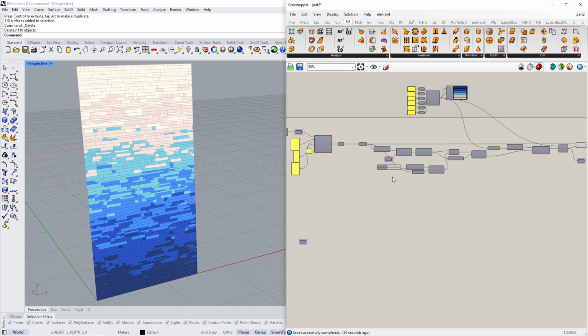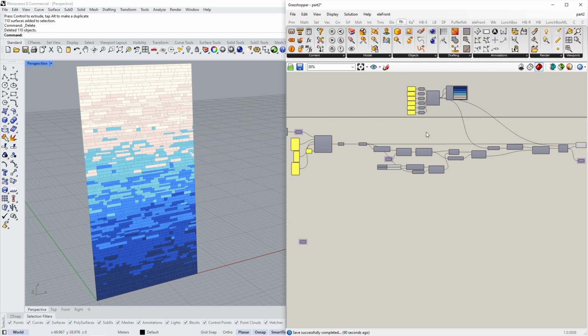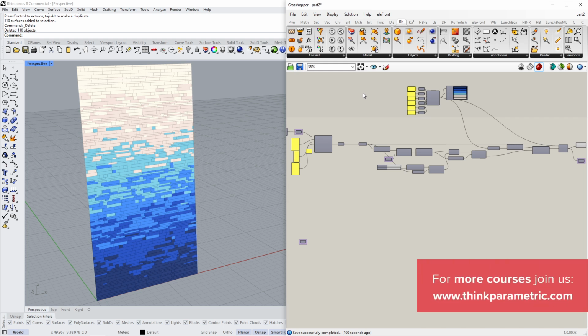And we're going to take a look finally into this new tab from Rhino, which is now included in Rhino 8. And all these components you see here in the Rhino tab, they all let you interact directly with the Rhino document. So either geometry that's already located in the document, but also you can add layers, remove layers, change a lot more stuff.